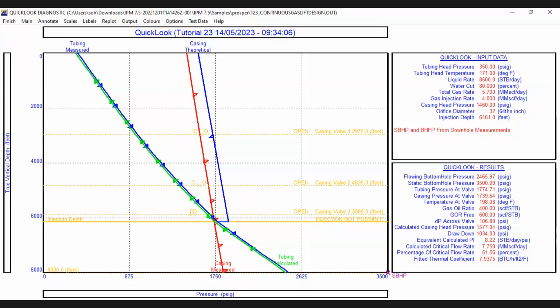In order to calculate this, the associated or theoretical produced gas rate, we need to know our liquid rate, our GOR, and our water cut. I hope all of you know the formula. Our liquid rate is about 8,000 something, multiplied by the GOR, which is 400, and then multiplied by 1 minus our water cut, which is 0.8.